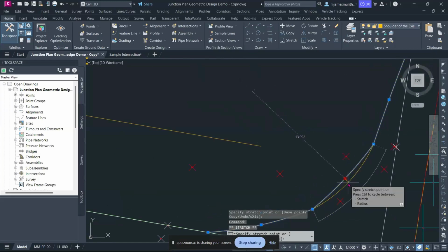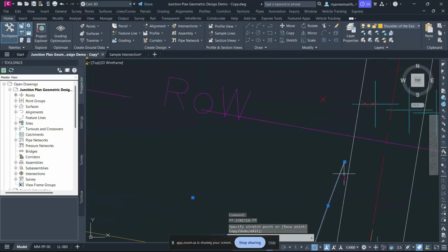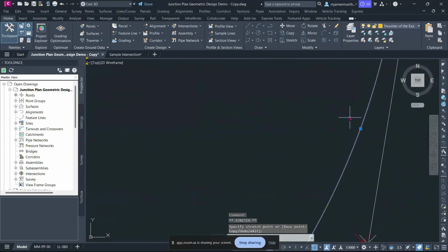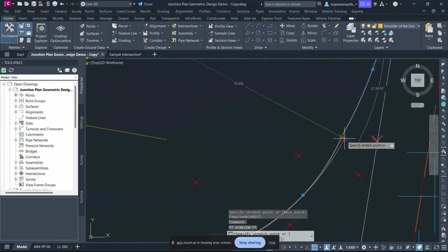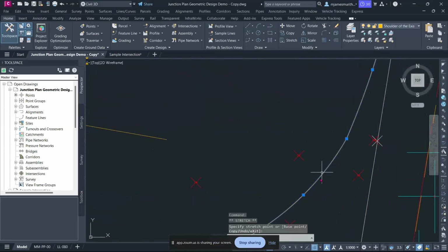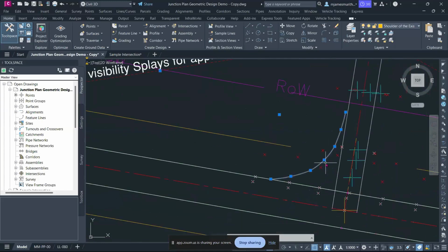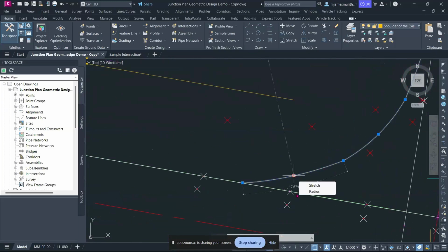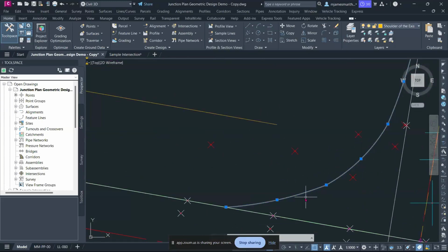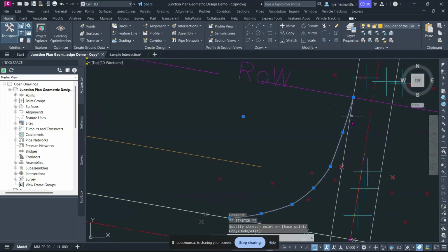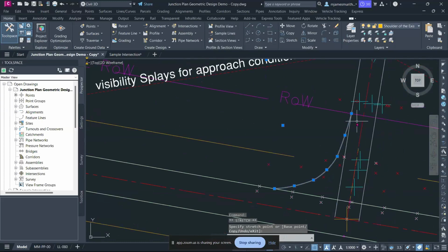Remember, you've already understood the largest vehicle that will be turning here. I remember the radius that we were given was something between 12 to 15. But of course, something that is bigger than that would still work. So for example, this is the most important radius, the turning radius, 17. So ideally this is cool. And then I look at this other one. This is 37, fairly good. And then I look at this other one. This is 53. This one is allowed to be extravagant. And then I can taper it back to where it meets the road section.